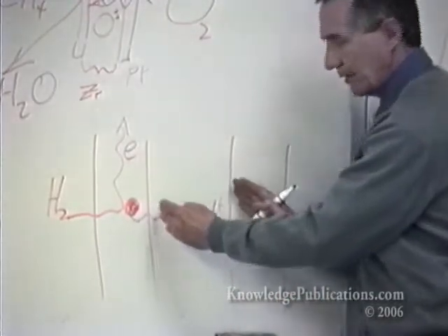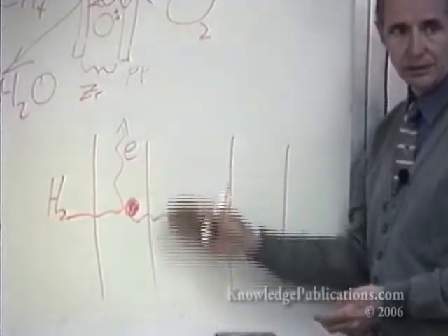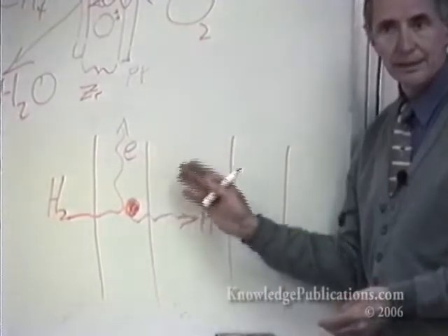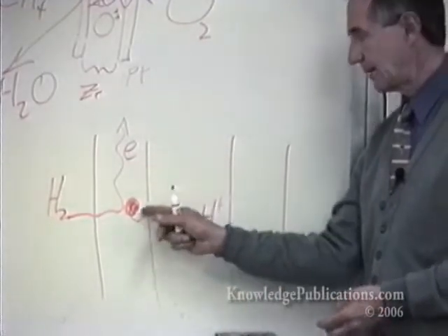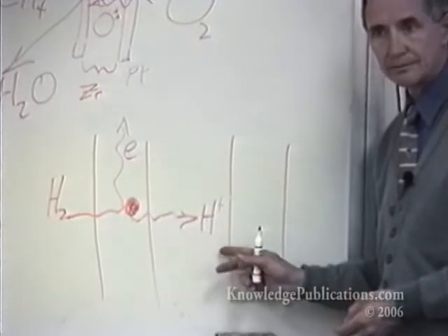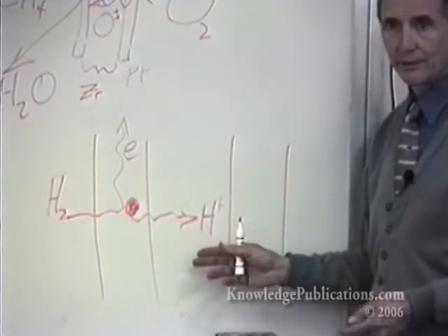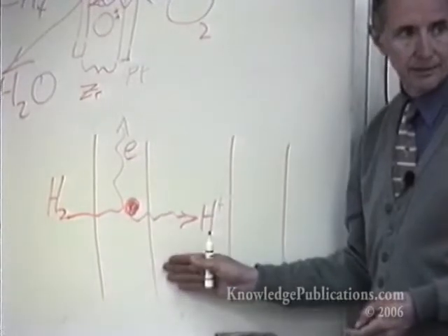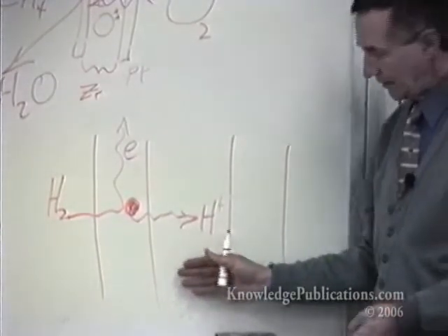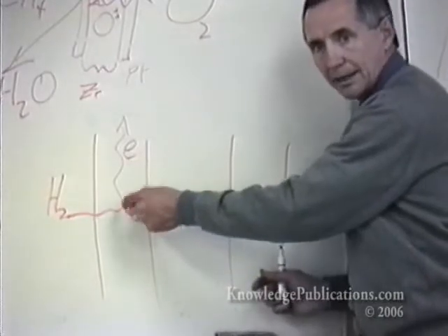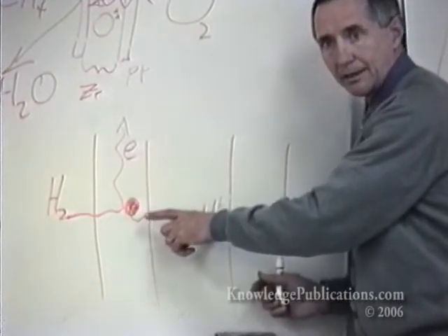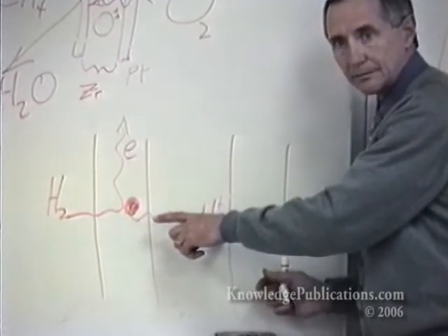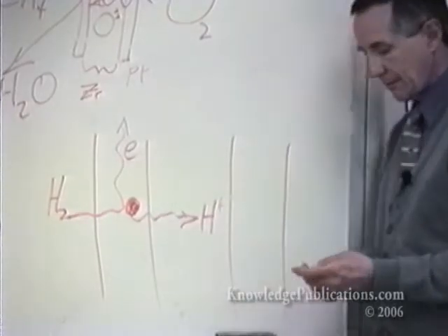In order to reduce the ohmic loss of the membrane, what you'd like to do is to make as thin a membrane as you can afford and still not get gaseous hydrogen across it, or whatever your fuel may be. You want to avoid the giving away of the potential energy to the oxidant by blocking anything but an ion that you produced. So the thinner the membrane, the better you are. Yeah, for ohmic losses, the thinner the membrane, the better you are.